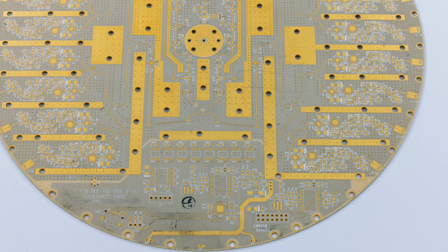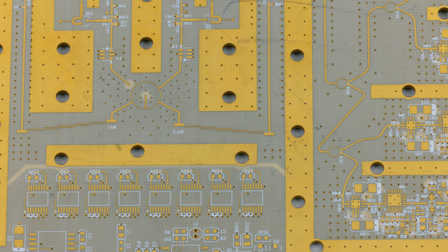Some drawbacks are the performance and repeatability depend upon the tolerances of the inductors, capacitors, and resistance of the lumped elements that are used. The second essential type of filter is the planar transmission line filter. This type may be the favorite filter for the engineers here at MPT. In fact, our engineers have developed numerous types of planar filters.